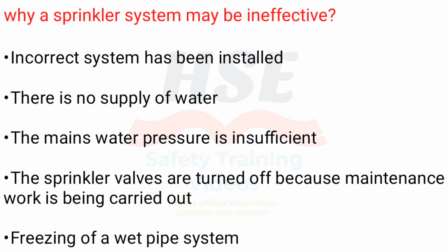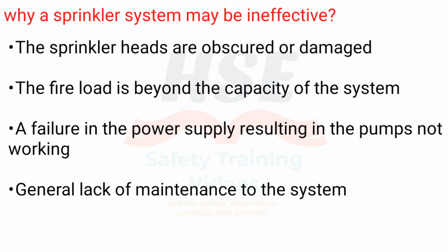Freezing of a wet pipe system. The sprinkler heads are obscured or damaged. The fire load is beyond the capacity of the system. A failure in the power supply resulting in the pumps not working. General lack of maintenance to the system.